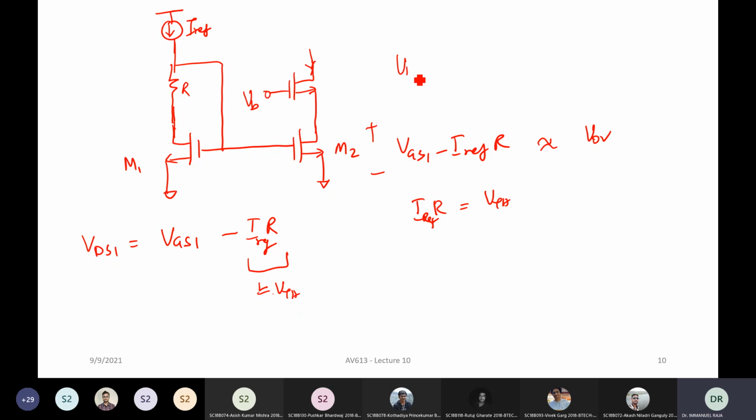This V can be written as nothing but the VD sat. Basically, it should be taken such that it is VDS1 plus VGS3. That's all. Now, what happens? Your V out min should be equal to 2 times VD sat. Or if you use the older classical equation, you basically have 2 times overdrive voltage. Okay. All right.